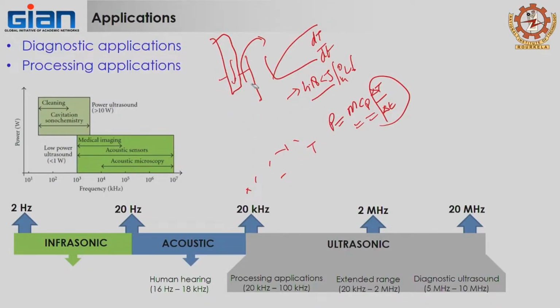So this way you get your watts, then you know the diameter of your probe, which gives the ultrasonic intensity. Whereas when it comes to a bath system, the radiating surface is bigger. So the power will not be the same between a 200 watt probe system and a 200 watt bath system, because the ultrasonic transducer is attached to a flat surface and the whole surface is radiating. So intensity is reduced. That is why comparisons are not easy to make between a bath versus a probe.